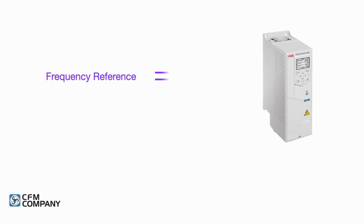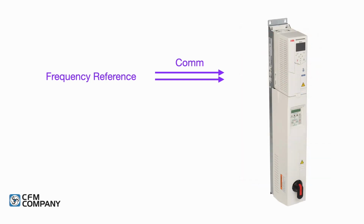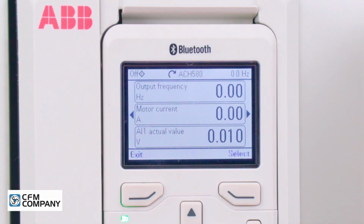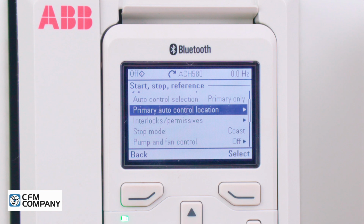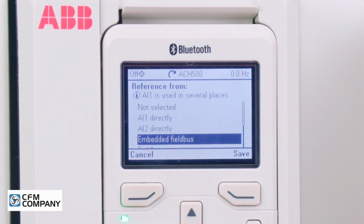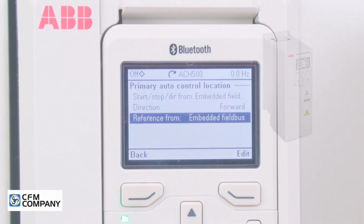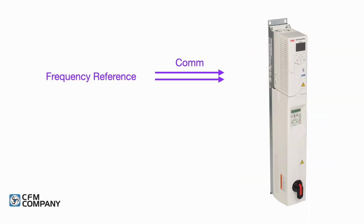The frequency reference can be sent over serial communications. These instructions apply for all ACH580 models with or without an Eclipse bypass. Use the ACH580 control panel. Press Menu. Select Primary Settings. Select Start-Stop Reference. Select Primary Auto Control Location. Select Reference From. Select Embedded Field Bus. Press Save. The reference from should now read Embedded Field Bus. The drive is now programmed to receive a frequency reference from the Embedded Field Bus, EFB.